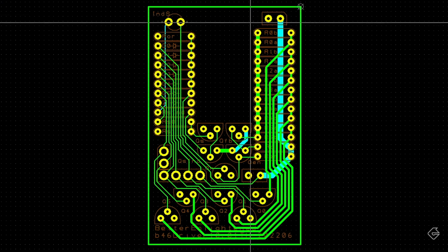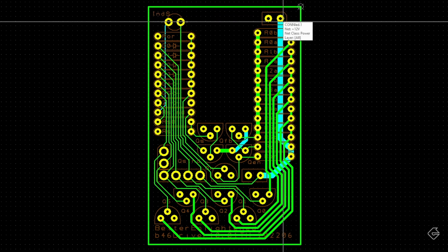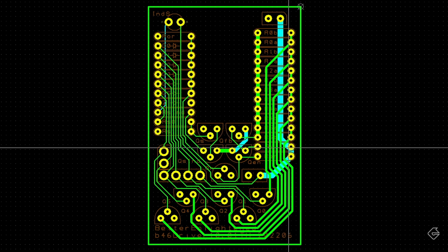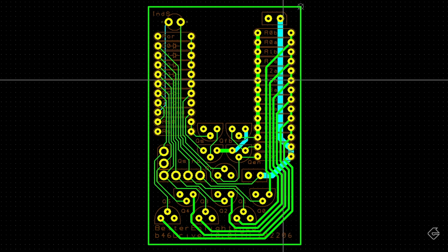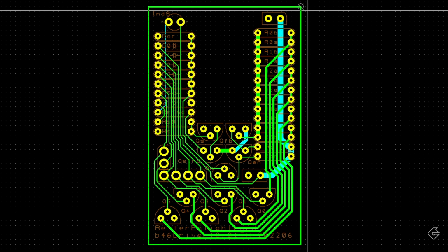Now these two connectors on the PCB are going to lead to the actual LEDs that we're going to mount wherever they happen to be mounted to. And here's the connection over here. And just like before, you can see the nice fat trace that I put in here because all of that current is going to be flowing through that trace.